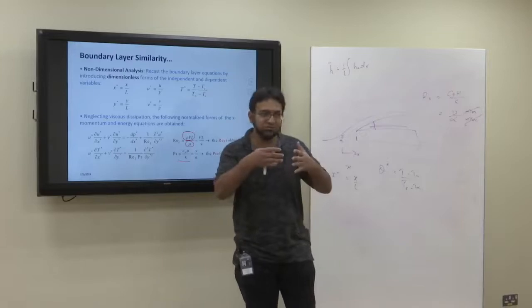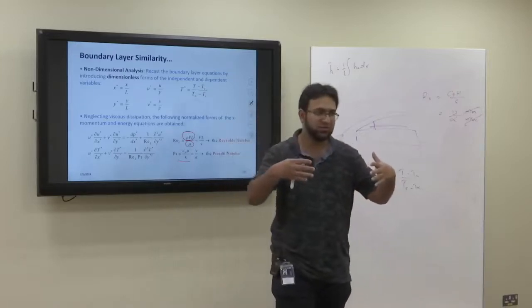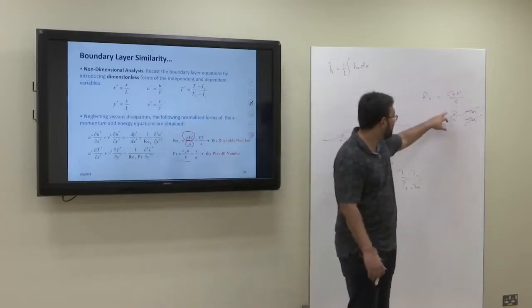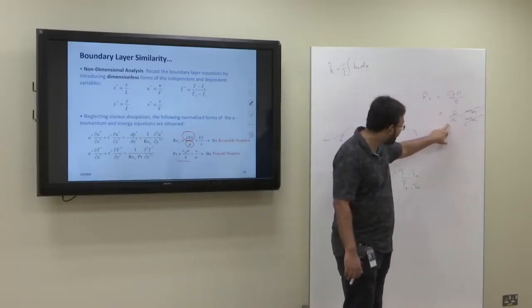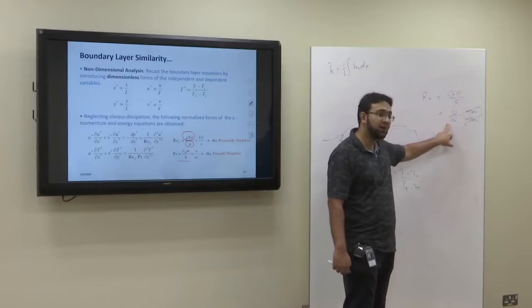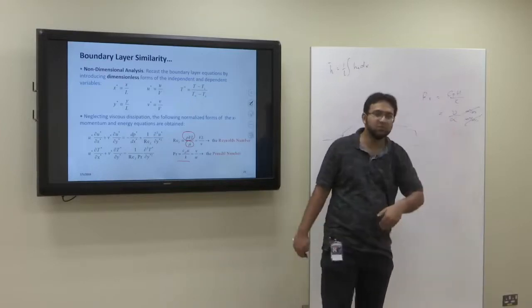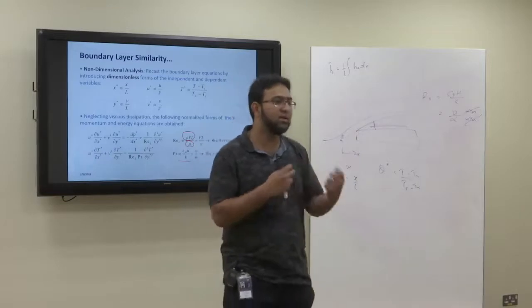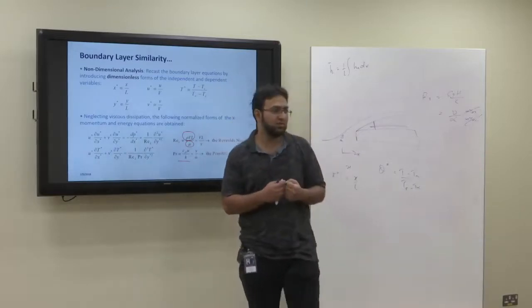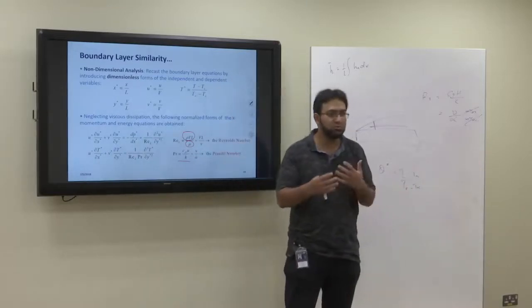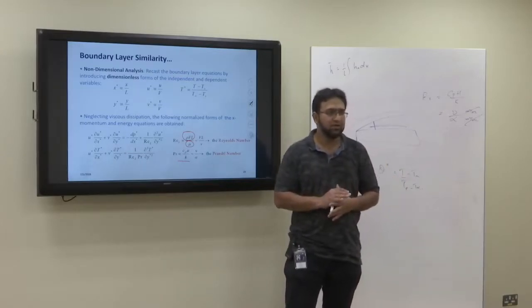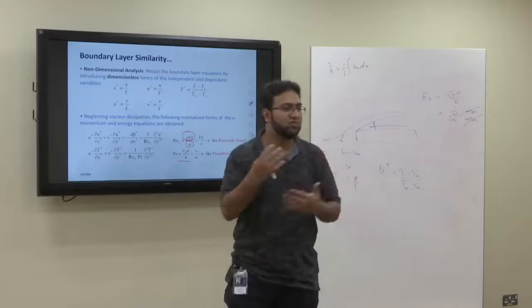So momentum diffusivity will be slow. Okay. So in that case, your momentum diffusivity will be less, and the thermal diffusivity will be high. So Prandtl number will be less than 1. So Prandtl number is a ratio of how quickly the momentum diffusivity occurs compared to how quickly the thermal diffusivity occurs within the fluid. Okay. So it's a ratio of two diffusivities.